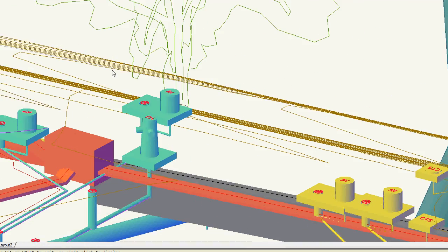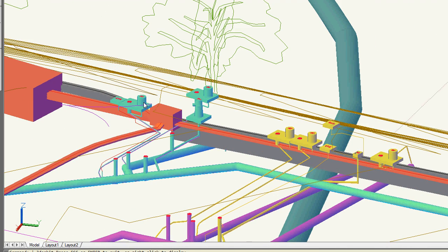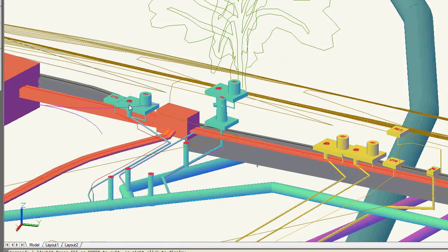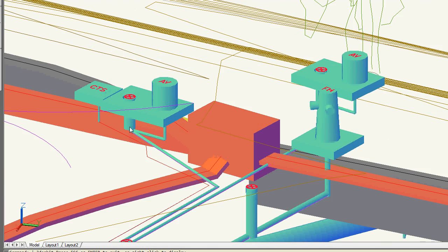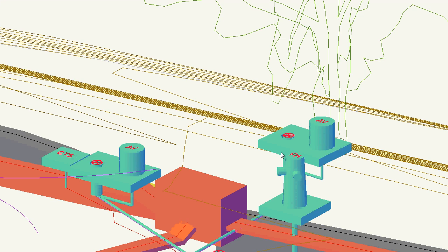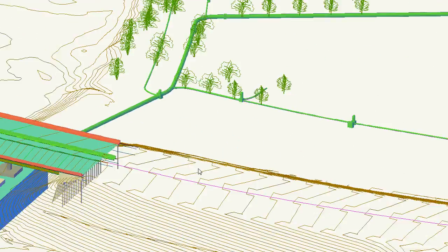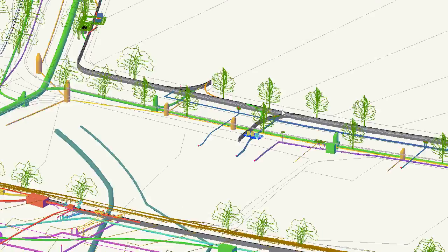Because on a plan, an air vac might look like a little triangle or a circle for a blow-off, but when you actually start drawing out the laterals and what the copper pipe's going to look like, more or less, because it is flexible, you discover sometimes these things take up more area than you expected, and you have dry utilities to contend with. So got a lot of stuff going on. There's actually a pressure reducing station over here.